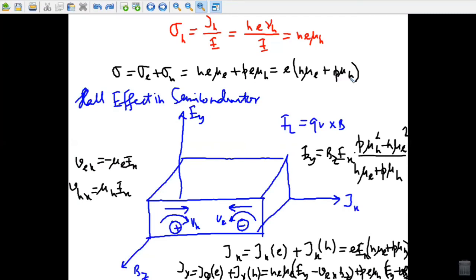And there obviously the effect of temperature on mobility, the T to the power 3 by 2 law, that we'll discuss later. Now, a very important concept, what happens for the Hall effect in semiconductors. We have so far discussed the Hall effect for metals containing electrons as charge carrier. The same treatment is valid for extrinsic, whether it is p-type or n-type semiconductors, where the majority charge carrier is either electrons or holes. In the following, we shall consider the case of an intrinsic semiconductor where simultaneously both electrons